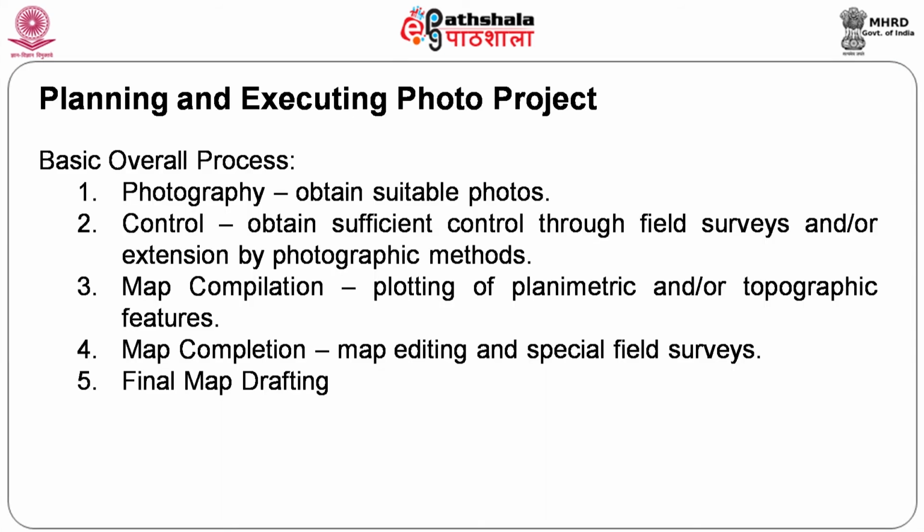They place the control points on the surface. We will see the details a little later. At the time of photographing itself, we get the detail. If I have that detail, I know its position because I have placed it there. I have kept the control there. Then I can identify it, and if I know its XY, automatically I will be in a position to get the XY of the aerial photograph.